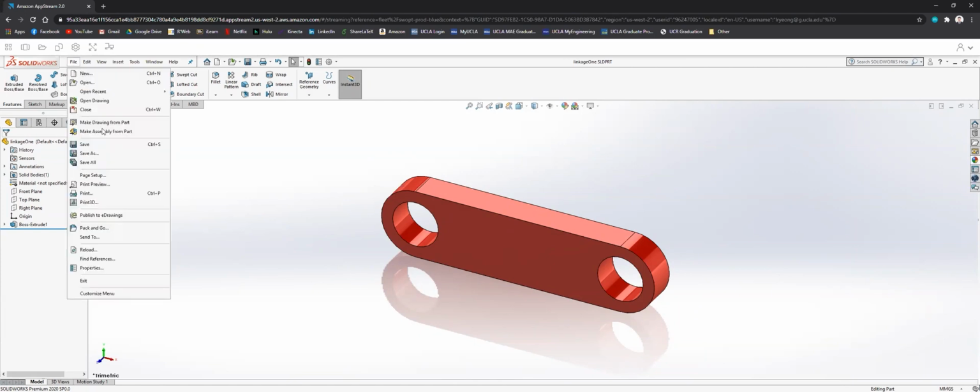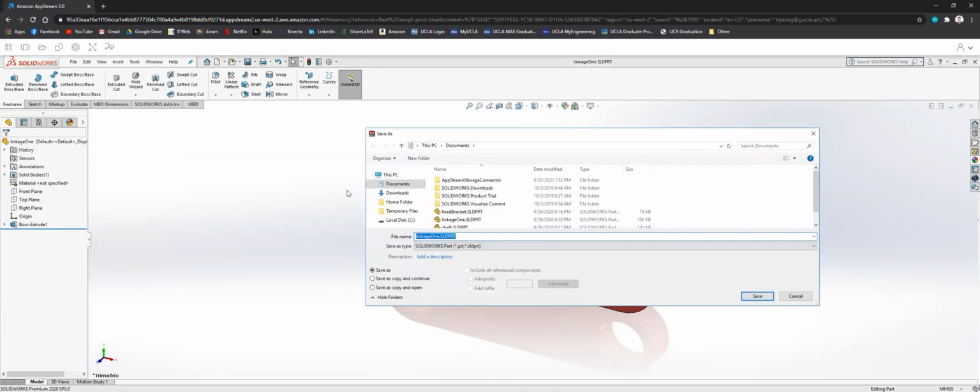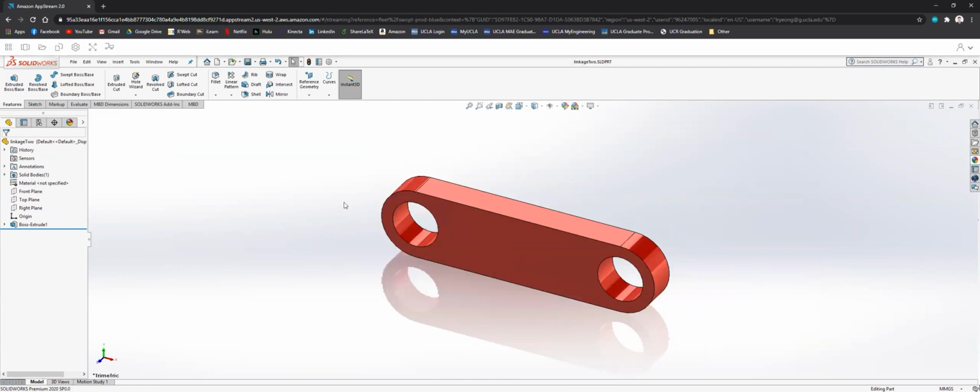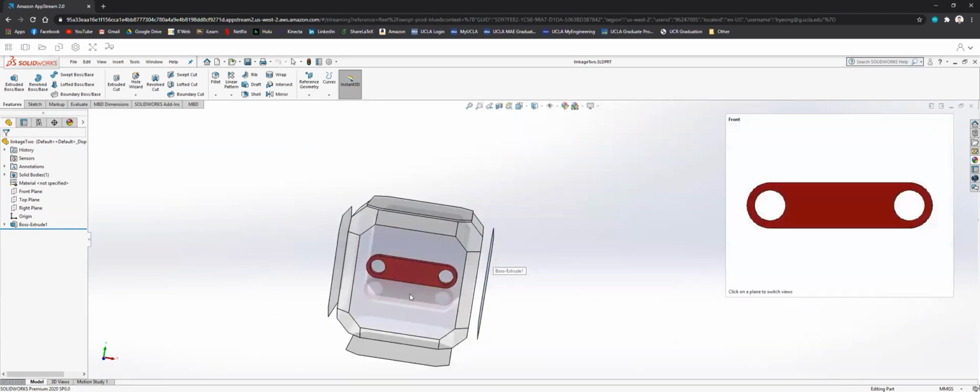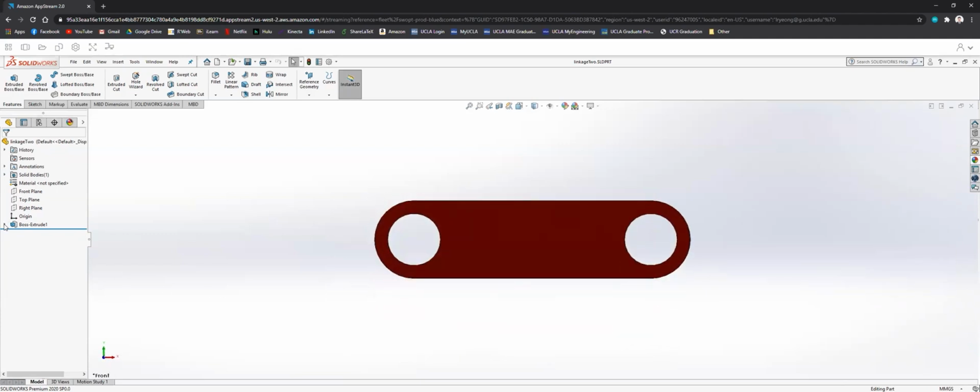So what I'm gonna do is I'm gonna actually save as again, because I'm creating two linkages, so they're basically the same shape. So I'm just saving as again. So this is linkage 2. But linkage 2, I'm just adjusting a parameter. So if I go to the sketch, what we sketched before, I can right click on it and edit that sketch.